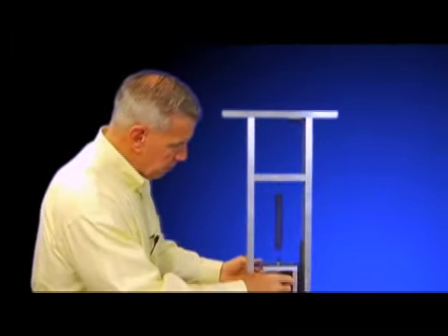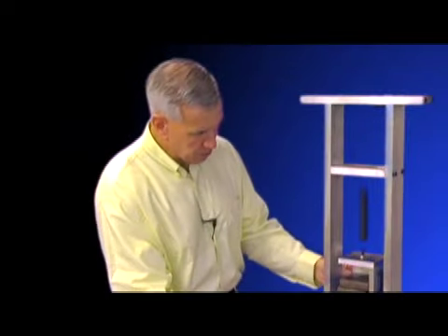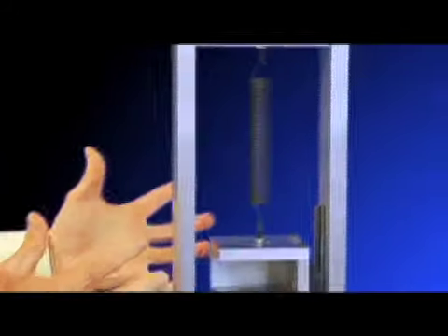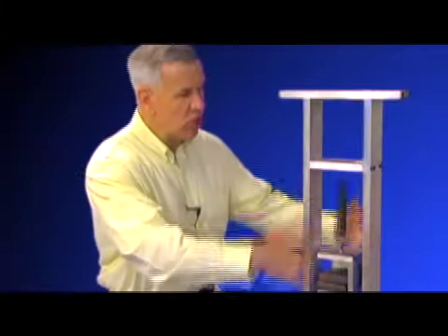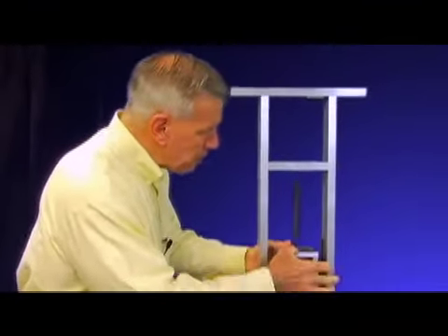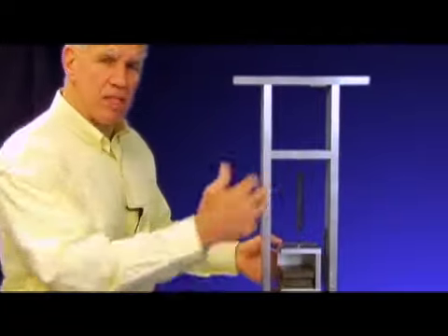Moving down to the mass, again, I treat it as being rigid. It's a tray of aluminum with steel blocks that I can add or remove. Because it's a rigid mass and it's constrained to move up and down, I can treat it as a point mass. It doesn't rotate, it doesn't move out of plane. It translates up and down in 1 degree of freedom motion. What constrains it for that motion? The linear bearing, the translational bearing, which consists of balls and a track with oil, again, allow it to just move up and down. Constrain it to move just up and down.